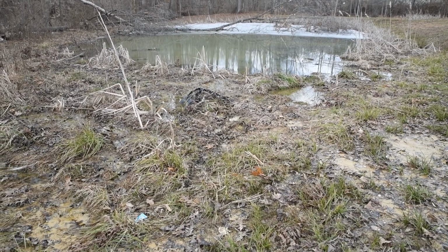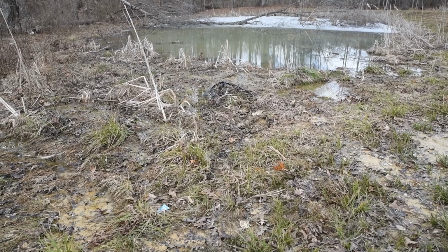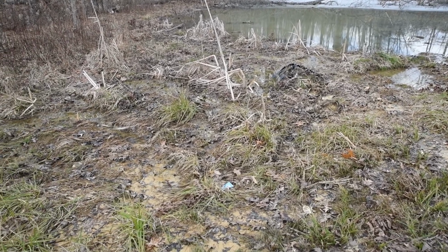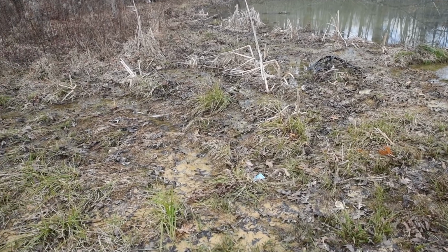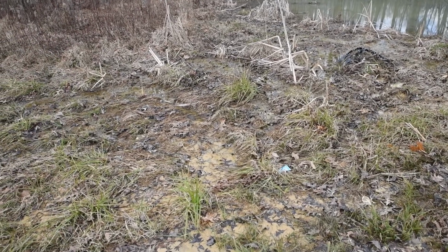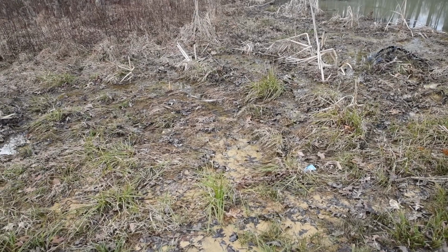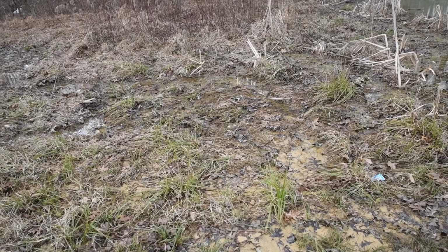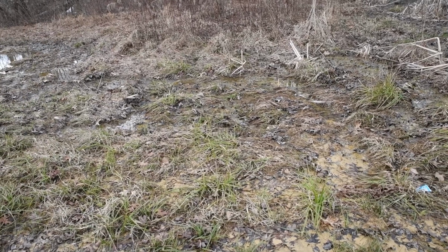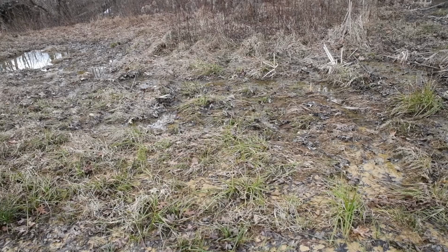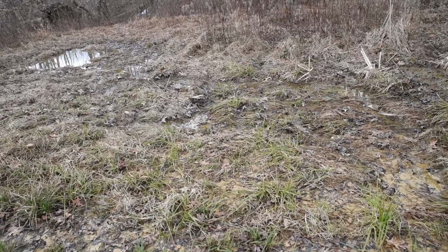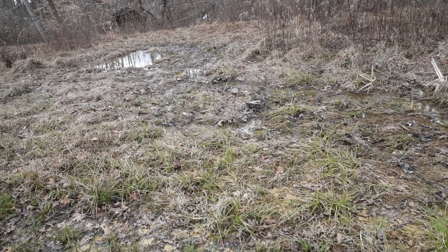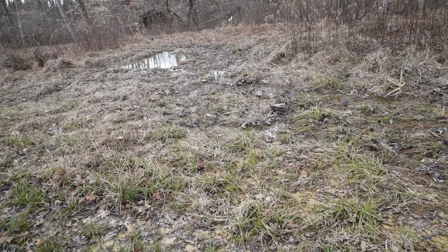During a storm, water quickly fills the wetland, and then it begins flowing out the spillway that we constructed. Water entering the wide spillway quickly spreads out in a sheet-like pattern. This spillway is about 20 feet wide and it's level in cross-section. It was built on only a 1% slope. There is no defined stream channel in the spillway. The soil in the spillway is saturated and the spillway has become a wet meadow wetland. This wet meadow wetland supports a diversity of flowering plants that are used by pollinators.